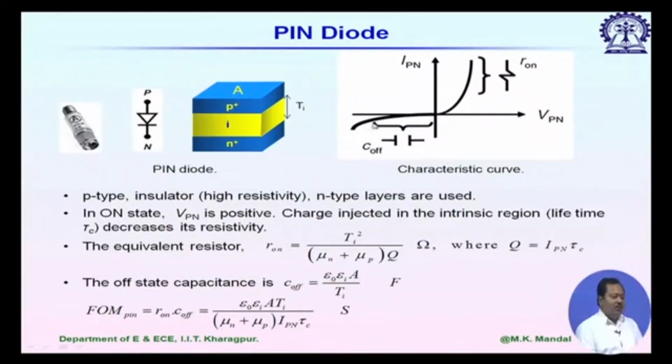So, this shows the VI characteristics of a PIN diode in forward biased condition. This is the DC characteristics, not the high frequency characteristics. In forward biased condition, it obeys diode relationships, also in reverse biased condition, but if we keep on increasing frequency, the working principle becomes different, and in that case it does not obey this diode relationship.